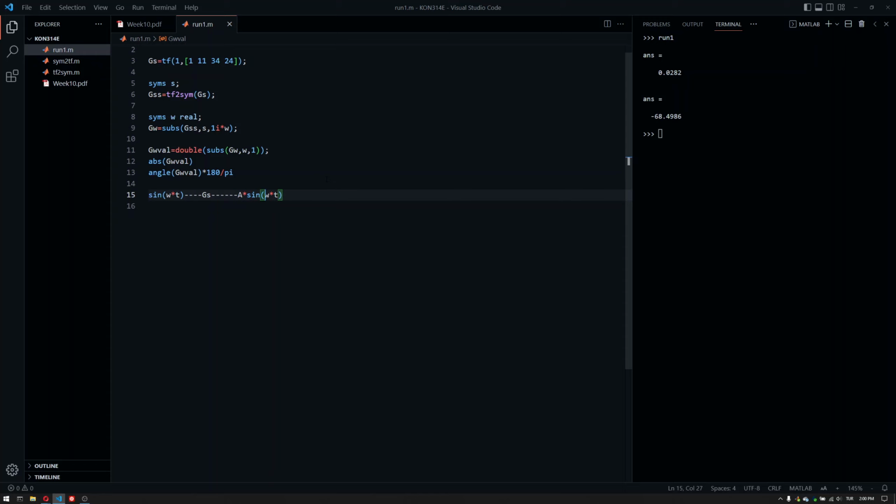It will have a different gain, it will have a different phase, but if you know the frequency domain signal systems, or other lectures may also have taught you, the frequency only changes when the frequency of the source changes. So when you have omega t, if it's a linear time invariant system, it will still be omega t. But the gain and the phase will change.